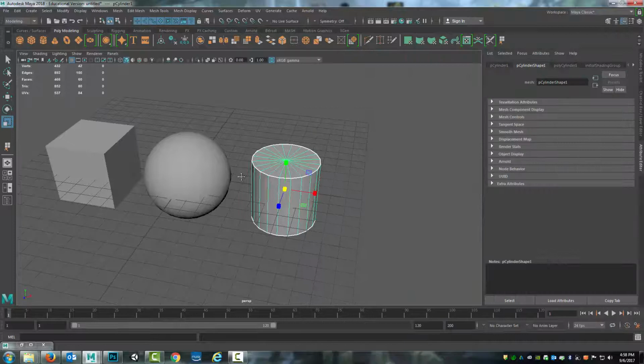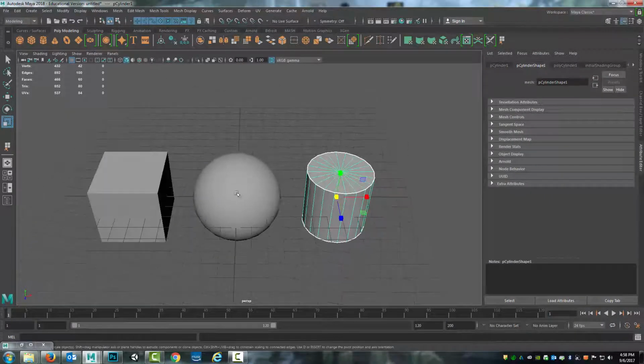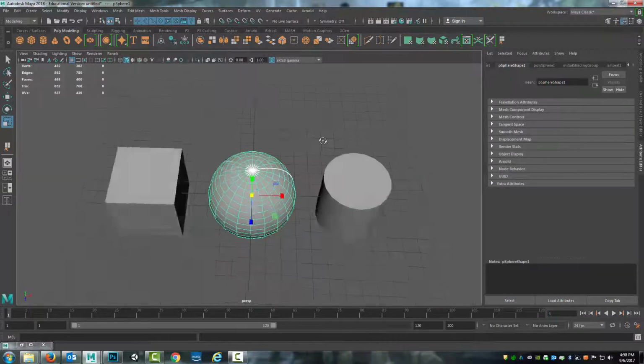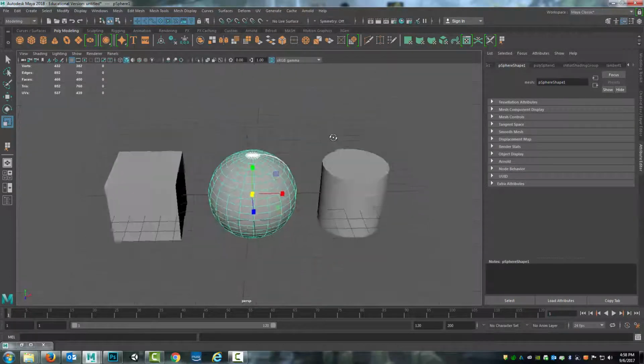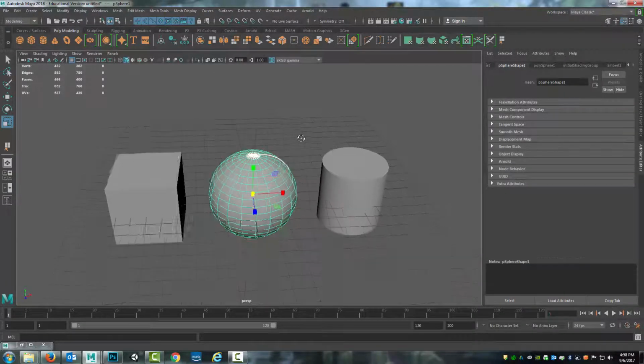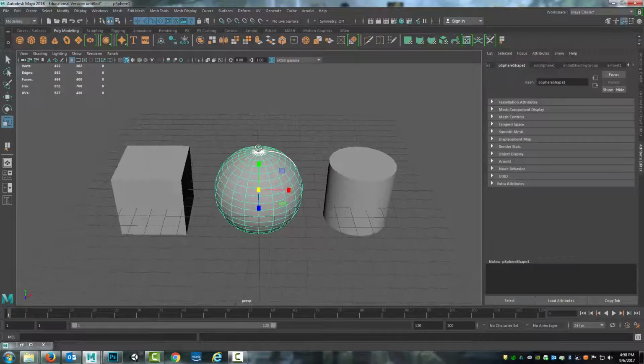Now the way this becomes practical is when we start creating and applying materials. By default, as we've talked about before, there is a Lambert 1 attached, or in the case of Maya Light, I'm trying to remember, either a Blinn or a Phong one, but it's a default material, and we want to get away from using default materials. They don't play well in most game engines or rendering engines, and so you really do want to have custom materials and custom textures for each of the objects.